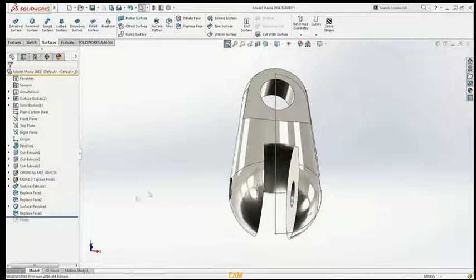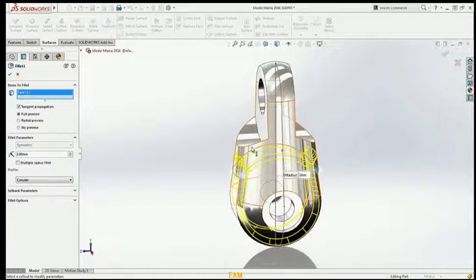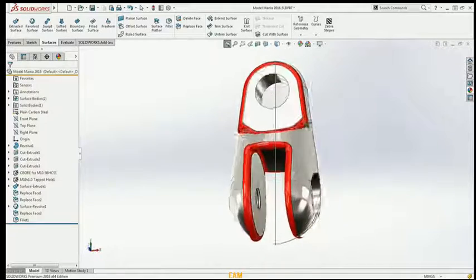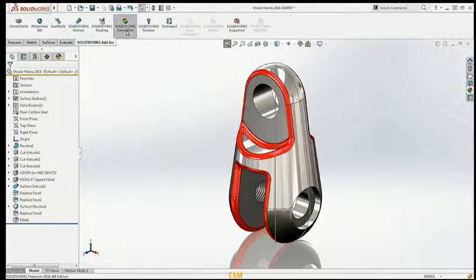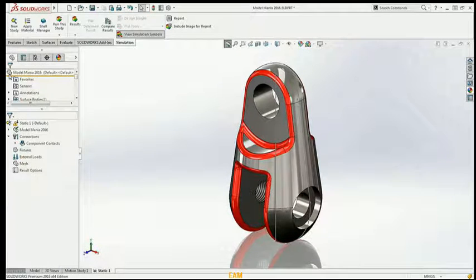Hide that surface. Now we got to deal with our fillets. Well, all those faces have changed dramatically, so we got to deal with fillets. Remember, before all I did was choose 3 faces, so we'll just reselect those faces, get rid of the ones that we had there before, and there's your geometry for phase 2. Next, we ask you to run a simulation. Very simple simulation. We want you to fix the bottom 2 holes.